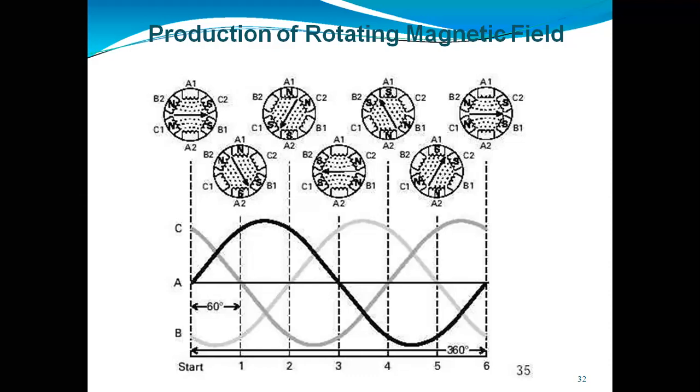At that time, when we are giving the three-phase supply, we have seen two adjacent phases are in 120-degree phase difference with each other. If you see here, A and B, there will be the 120-degree phase difference. And B and C, there will be the 120-degree phase difference. So when you are connecting like this, that motor will rotate in the clockwise.